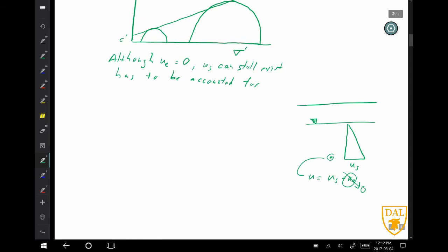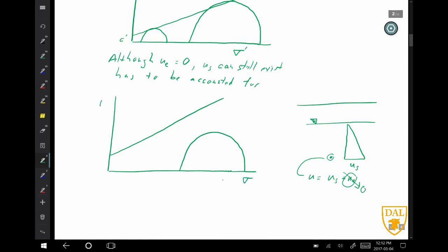Okay. All right. So let's draw that Mohr-Coulomb plot again, right? And so you had a failure envelope up here, and your stress state puts you over here in a happy place, which is well below the failure envelope. Nothing is touching it. But if you have enough excess pore pressure, or sorry, static pore pressure, that can cause, well, that's a very crude circle, but you get the gist of it.